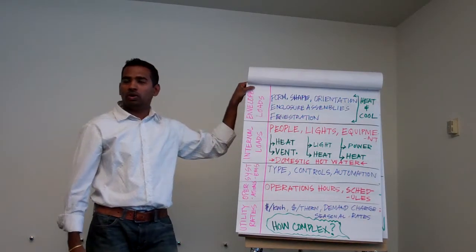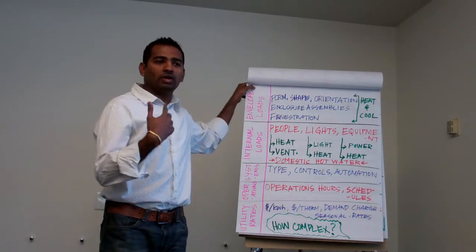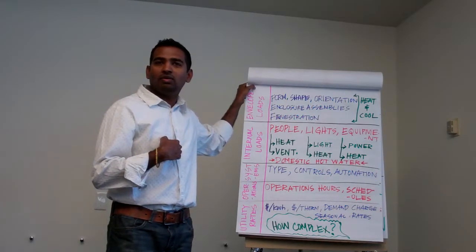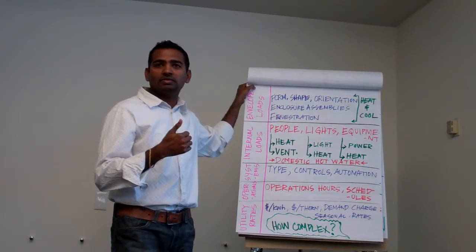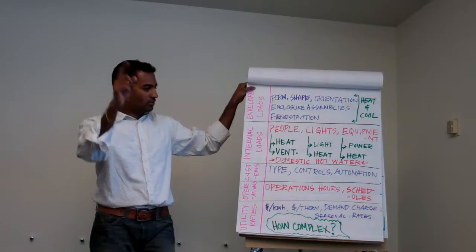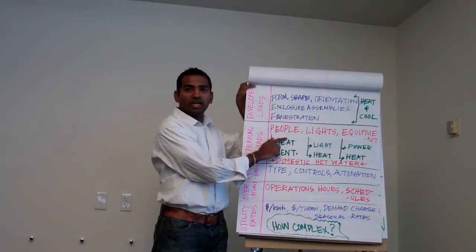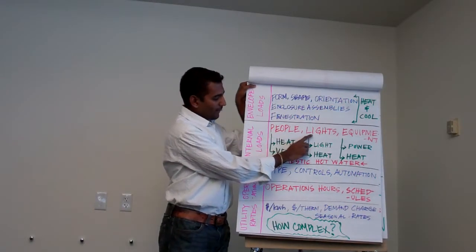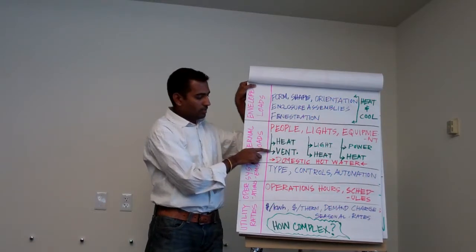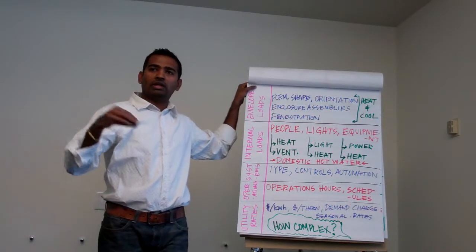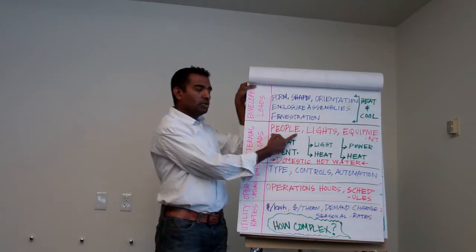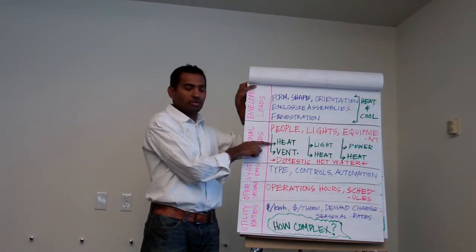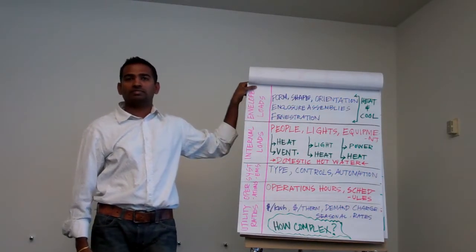Remember how much heat one person puts out? Do you guys remember from week 1? But what is that in terms of heat energy? 2 light bulbs. Good one. Yeah. So you have to cool that much energy for every person. So there's a heating part for people, but there's also a ventilation part, because we need to keep providing them fresh air. So if you have a huge number of people, you not only have to cool them with a lot of heat that they are producing, but you also have to provide them with ventilation.